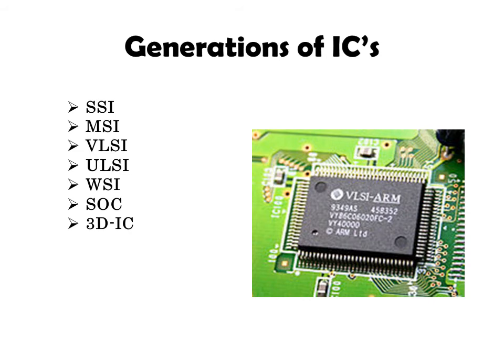The design of this device can be costly and extremely complex, and also building disparate components on a single piece of silicon could compromise the efficiency of some of its elements. The drawbacks of this device are offset by low manufacturing and assembly costs and by a vastly reduced power budget, as the signals among the components are kept on die, so much less power is required.